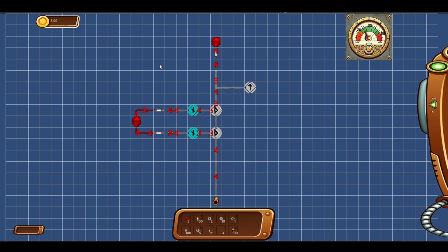And when you're dealing with something like the metal detector, you need to make sure that your power is even across both ends if there's no metal nearby, so that they'll cancel each other out. But if that's closer to one end or the other, then that side should have more power than the other side, and so it should end up coming out as a result. And that comes down to these transistors. But also, if you're using these cheap ones here, you need a capacitor, because you need to be able to make that flow consistent.